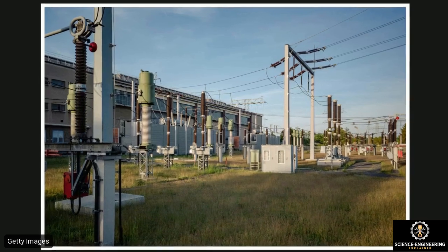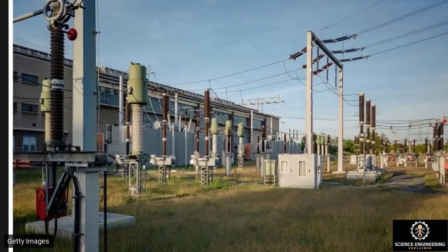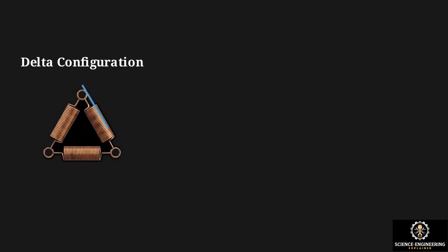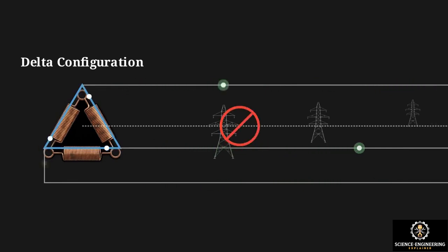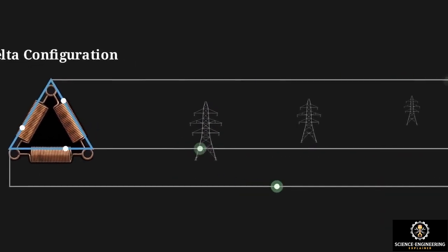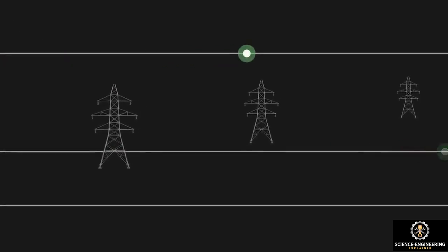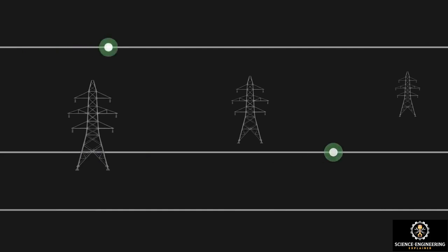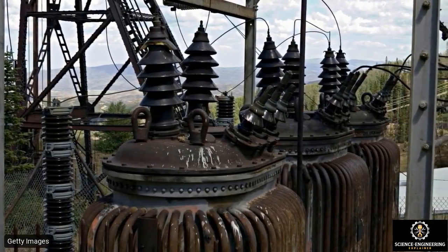This mathematical model scales to the high voltages used for long-distance grid transmission. Transmission starts with a delta configuration. The coils form a closed triangular loop that operates with just 3 wires. This leverages the zero-sum current math to omit the neutral wire over massive distances, which minimizes weight on the towers and reduces infrastructure costs. The layout changes at the local substation, where the grid must supply individual homes.